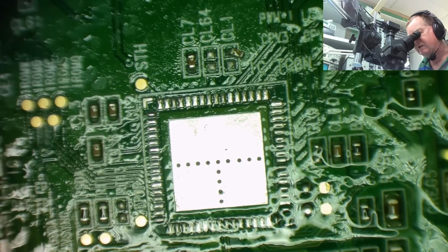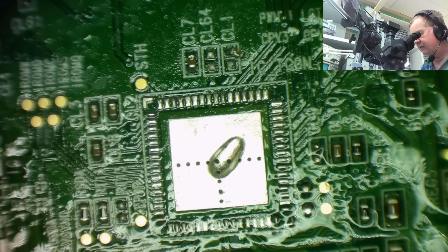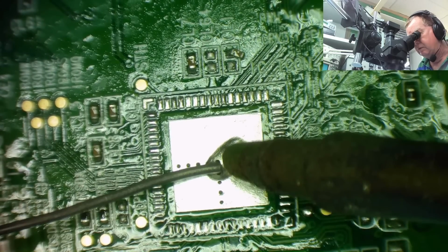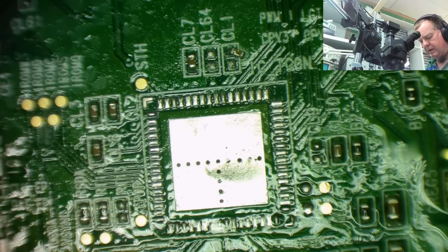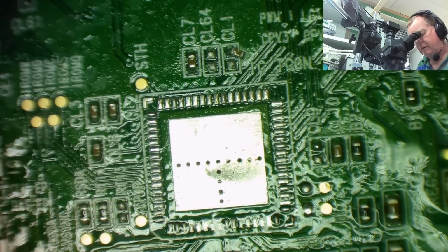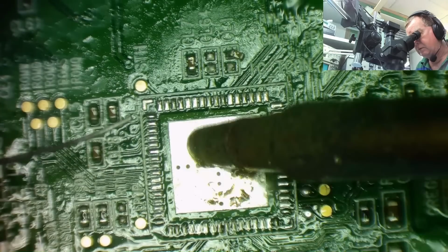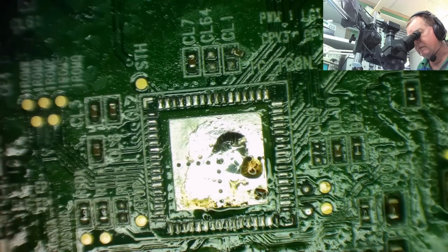But I need to get a little bit so that when we solder this back on, that'll kind of spread underneath it, yeah? It doesn't need to be completely under all of it, but use the thinner solder in fact, so we get a more controlled amount of solder on it. That'll probably help a lot. Yeah, that should do.